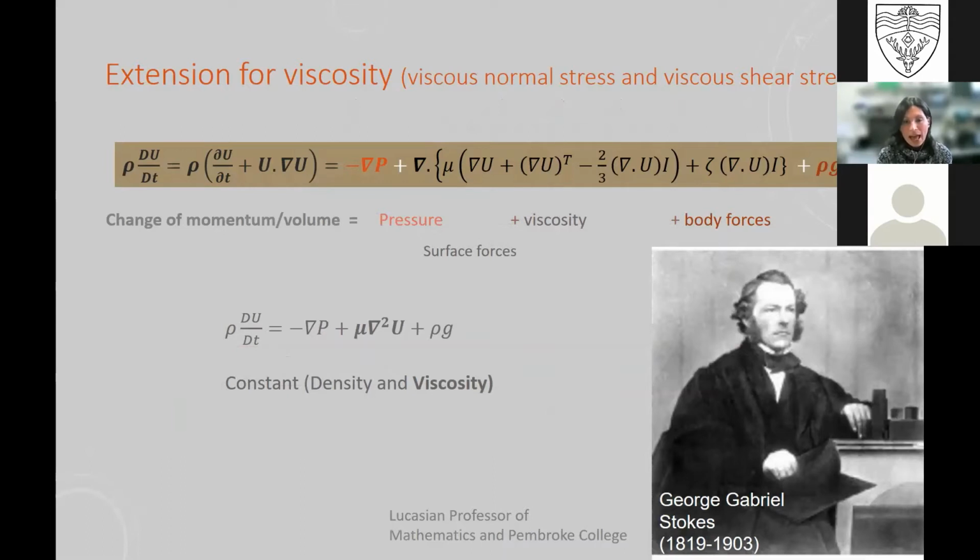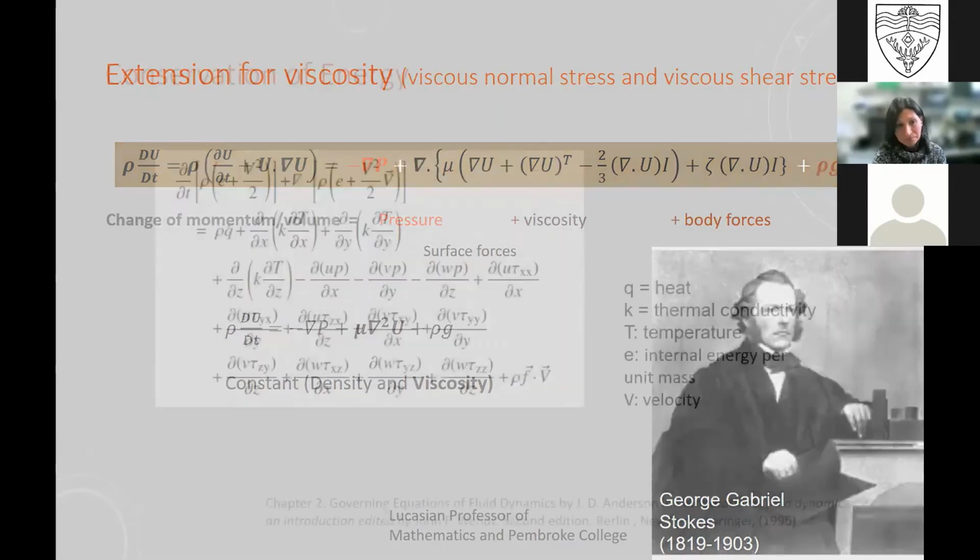And then we have a more complex bit of the equation to define the viscosity, basically, or that sort of relationship that I will mention in a bit. Pressure and viscosity, those are considered surface forces for the things we saw before. And again, this can get a bit simpler. For instance, if you have a constant density and a constant viscosity fluid, then this reduces to that expression there.